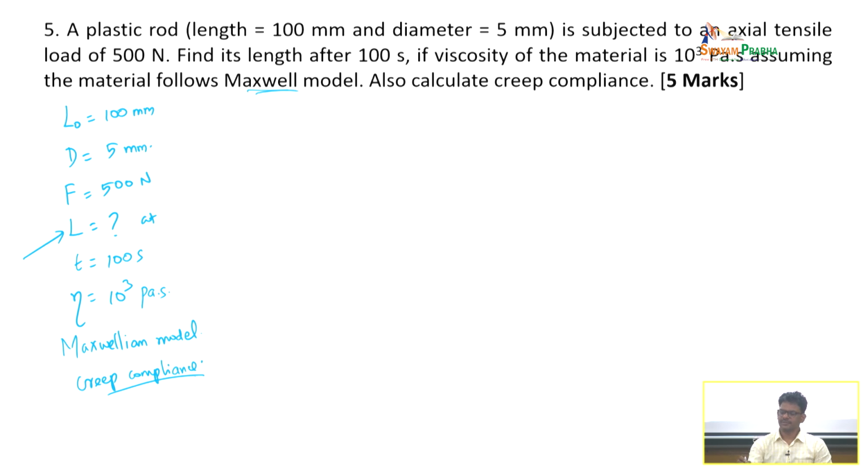The fact that I am asking for creep compliance means it is a creep test. That means you apply a load for a long time, and you look at how the elongation strain develops as a function of time. So, this is a creep response. Another possibility would be stress relaxation, where you give a constant strain and look at how stress develops. So, that is the first thing you have to decide: whether it is a stress relaxation or a creep response. It is a creep response obviously.